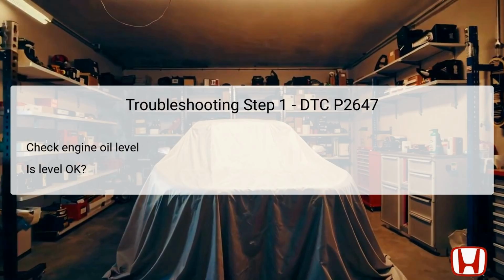The first troubleshooting step for DTC P2647 involves checking the engine oil level, which is crucial for proper oil pressure and the functioning of the rocker arm oil pressure switch. Low oil levels can lead to insufficient lubrication and pressure, causing the switch to send inaccurate signals to the PCM. If the oil level is found to be low, it's essential to bring it up to the manufacturer's specified level before proceeding to further diagnostics.